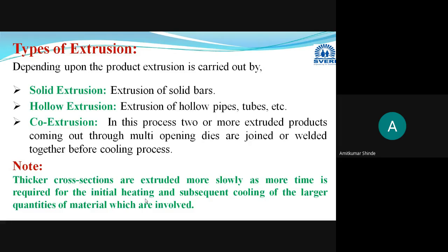Why? Because as thickness is more, more material is required, so you have to form a larger quantity of paste, and to form that larger amount of paste more heating is required, and at the end of extrusion it will take more time to cool. That's why whenever the thickness of the cross section increases, the time required for the extrusion process also increases.